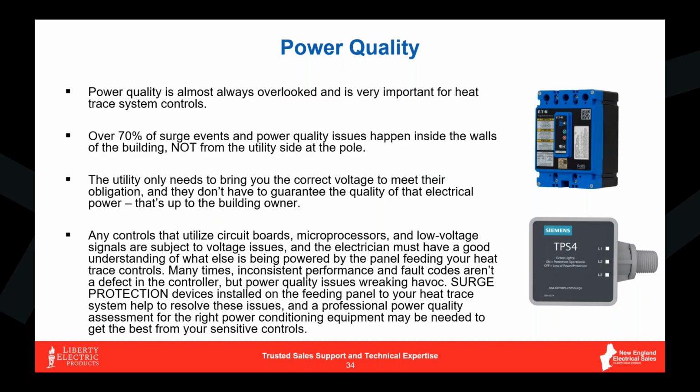We kind of lost sight of what's coming out of this panel, what's coming out of that panel. And there's that potential for signals to cross. So power conditioning, or really trying to make sure you can filter out a bit of that electromagnetic interference, improve your power quality inside the facility itself, will only help every microprocessor-based control you have in there.